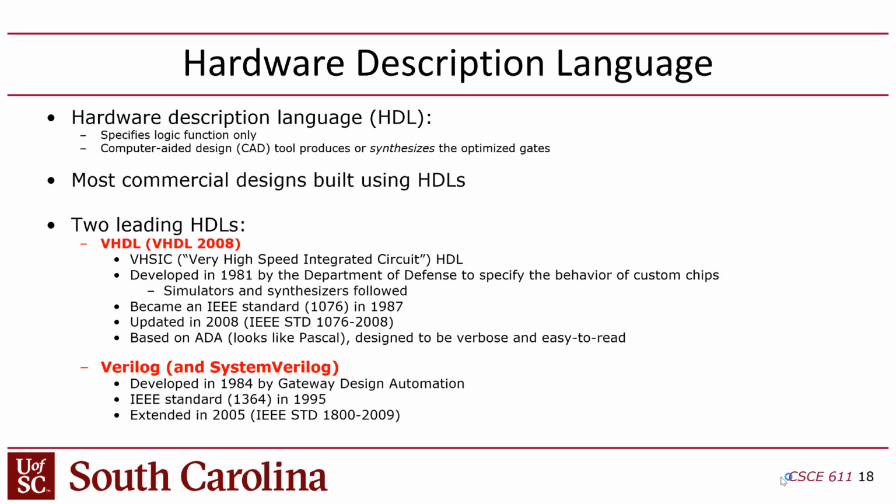And then eventually, they started building the simulators for the language, and then the really cool thing came, which was the synthesizers. The idea that you could say, here's a VHDL, and I'm going to lower it straight down to hardware and just make a chip from that. I could almost take the engineer out and have it automatically generate a design that matches the functionality of the description. So what you've got now is synthesis and simulation.